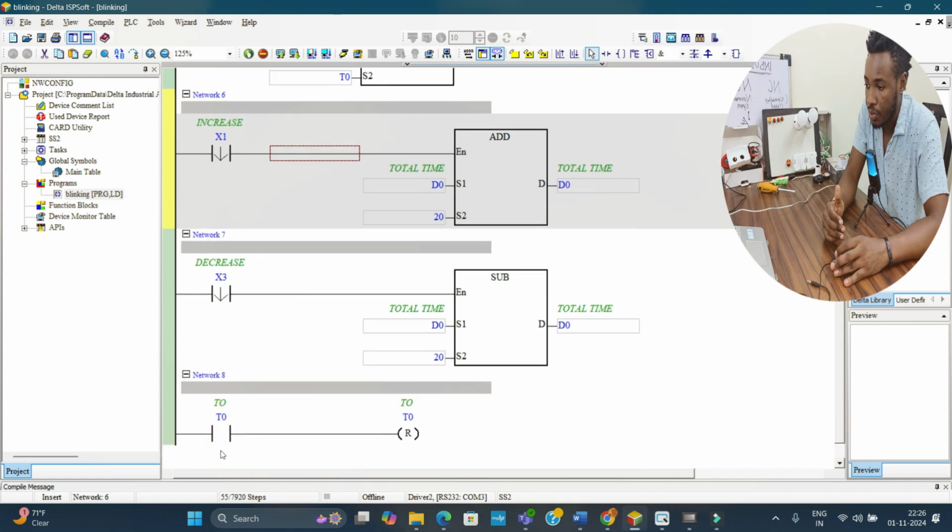And now after this, because if you do it up to this way without doing this step, this is to restart your timer, because whenever you finish, you have to restart the timer, and now the cycle repeats itself. So whenever T0 is showing high, it will restart the timer, so it will continuously keep in the loop.